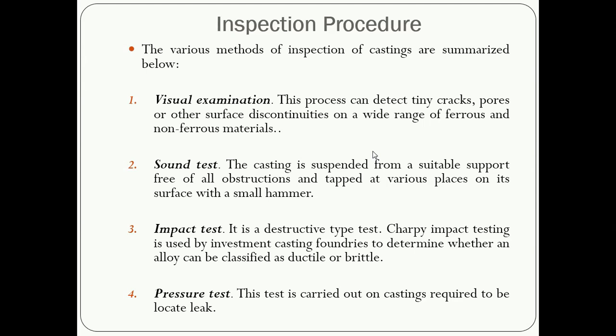All those inspection procedures need skill. The operator has to qualify some certification, then only he can go for the inspection. Next is sound test. The casting is suspended from a suitable support free of all obstructions and tapped at various places on its surface with a small hammer.